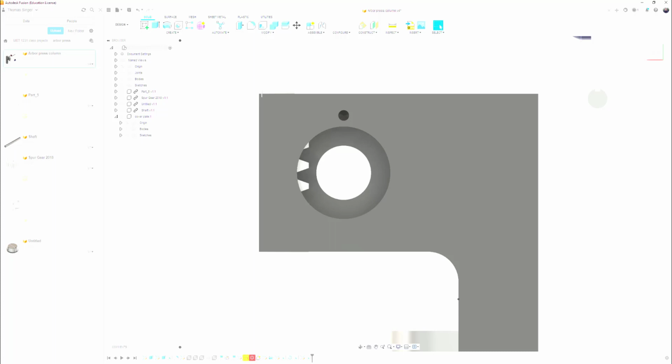So now you know what the length of the screw needs to be that you bring in: 8-32, about a 1/2 inch length. You have to give it a little bit of distance beyond the drilled hole, making sure that the drilled hole is deeper than the length of the screw so it does not bottom out in that hole.